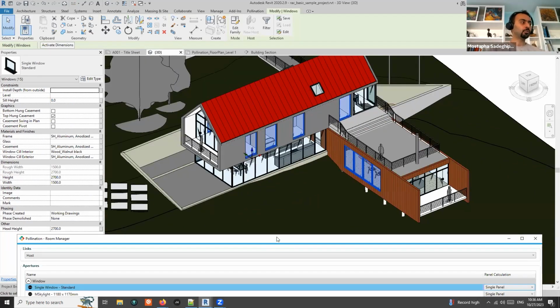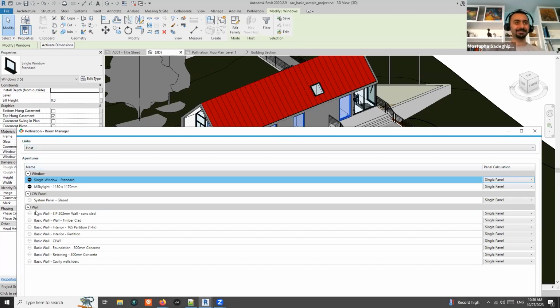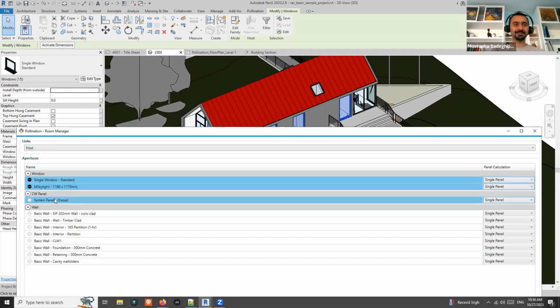And I know you will not do this with your models. You will come in and select everything and then go and render, and you see a lot of apertures on top of each other and things look weird. Then come back here and fix it. You spend a little bit of time here, but it just pays back for the rest of the project. Because if you clean up these windows and make sure you select the right curtain walls, you already saw we have the room geometry, then you get the apertures and you're like 90% there, just done, right? So spend some time here.